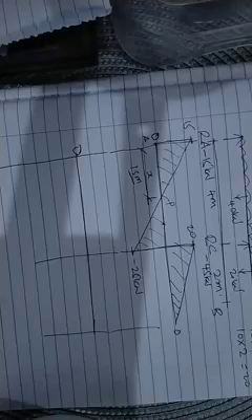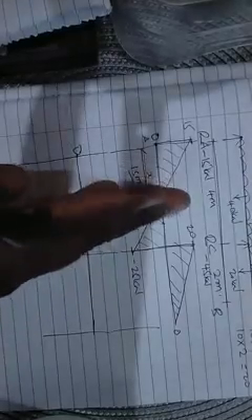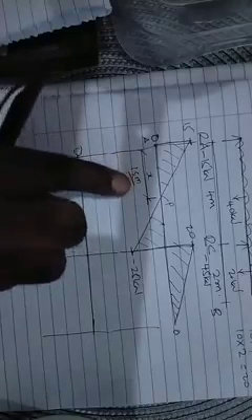So x is 1.5. So we have bending moment at P, and then we have bending moment at C. Those are our two critical points. So bending moment is simply the algebraic sum of moments at one point, considering either side of the beam, either to the left or to the right. So if we consider point P to the left, we are going to have a distance of 1.5.